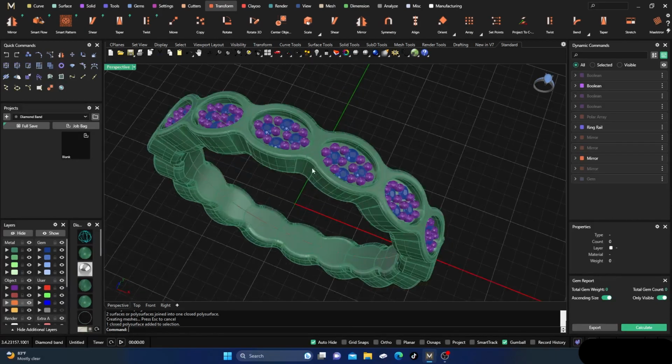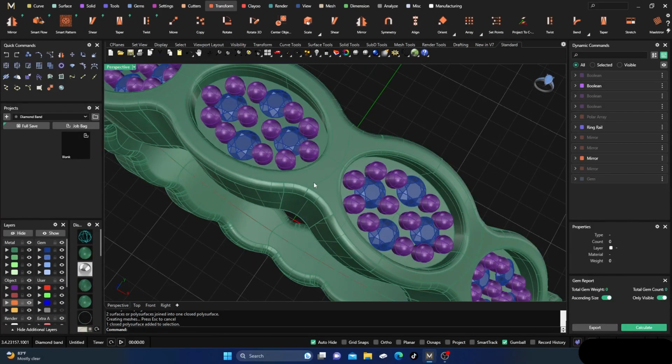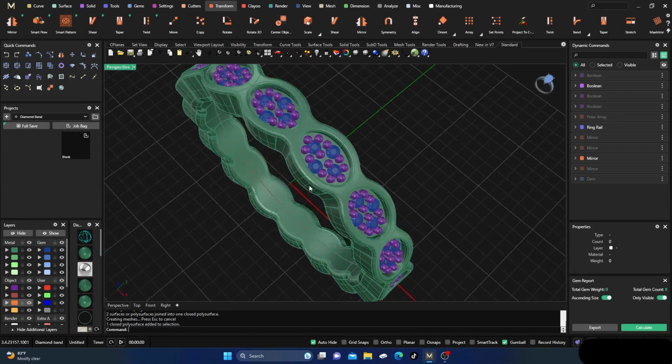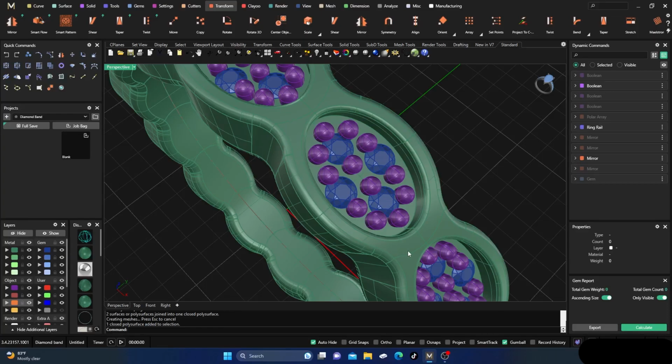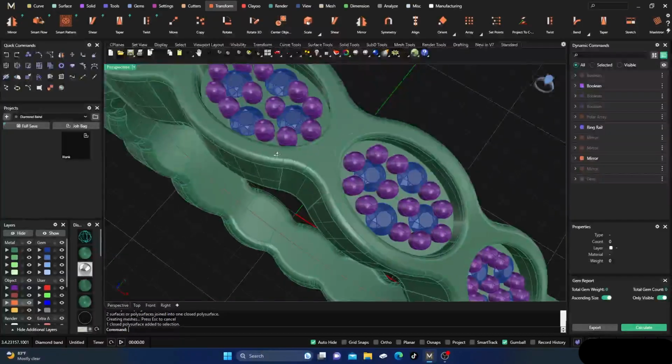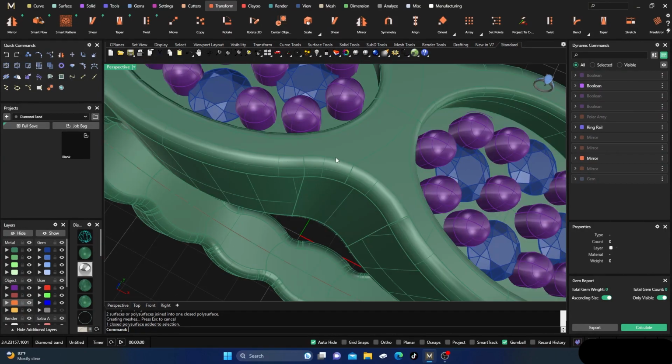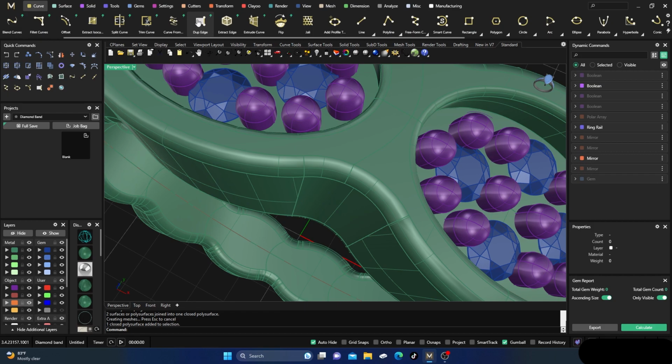Now, okay, so we have all this out there, but we want to give it that antique-ish type look, right? So we want mill grain or balls going around everything, right? Okay. So what we're going to do is, you can see there's a little edge there from that fillet, and there's the edge down here. All right. So what we're going to do is we're going to select the curve, and that's parametric dupe. I'm just going to do a normal dupe edge.